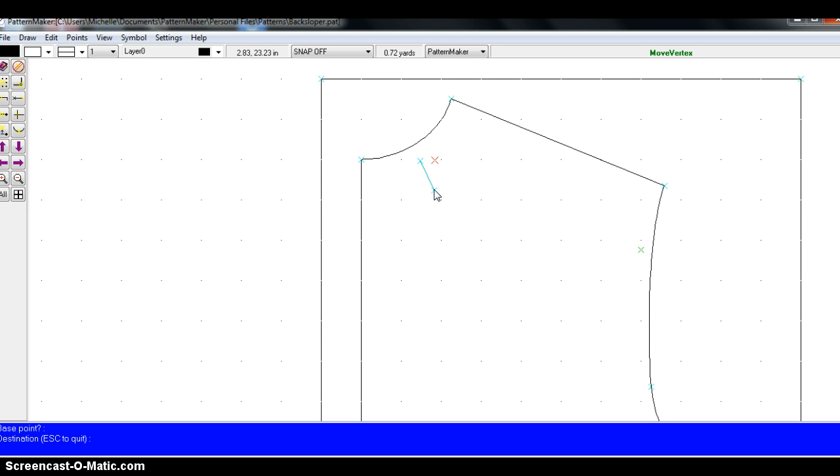Now, when you move the mouse, the shape of the neckline changes. Move it until the neckline takes on a reasonable shape. When the neckline is right, the corner point should be almost level or horizontal with the point you moved previously. Since the corner point, the end point of the arc, and the point below that one form a right angle, the neckline forms a square corner where it meets the center back line.